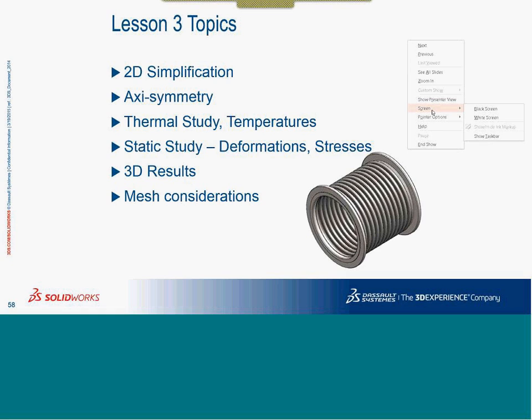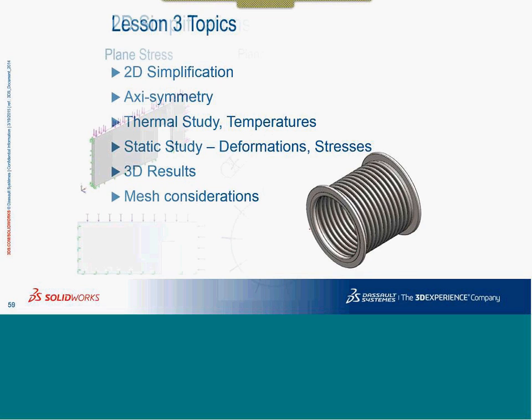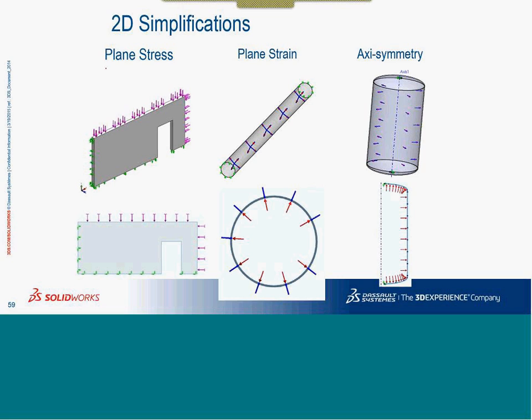There are simplifications in the software. One is axis symmetry, which is going to be used while we do the analysis work here, and the others are more towards this. One of them is called plane stress. The second one is more of plane strain.